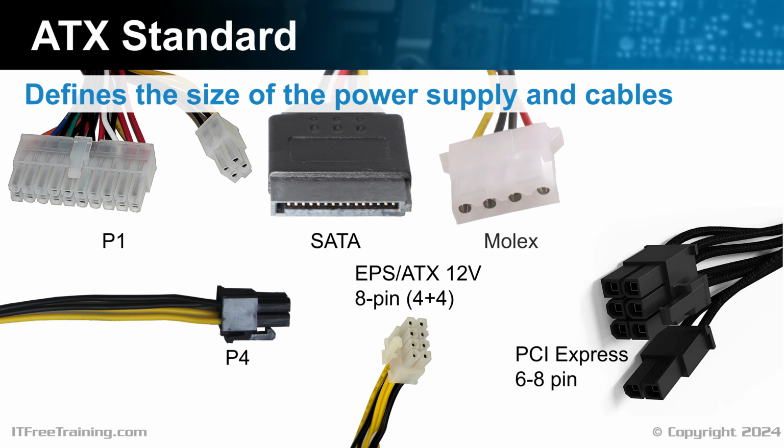Your power supply may also have Molex connectors. Molex connectors are used for older hard disks before SATA drives came along. They are also used for other devices such as case fans, although they don't tend to get used that much nowadays. They may also be used to convert into a power connector like a PCI Express connector. Since Molex connectors are used for older storage devices, your power supply may not have them.